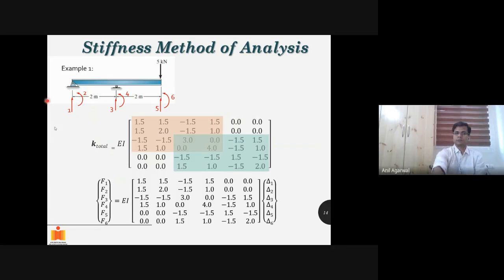That's what this stiffness matrix definitely means, that if I apply unit displacement at 5, there will be a force at 5, there will be a force at 3 onwards. Let me talk about this column. So if I apply unit displacement at 5, my force at 1 will be 0, my force at 2 will be 0. But forces at 3, 4, 5, 6 will be non-zero. So I'll have some force demands here, here, here, here, if I apply unit displacement here, but not here and here.